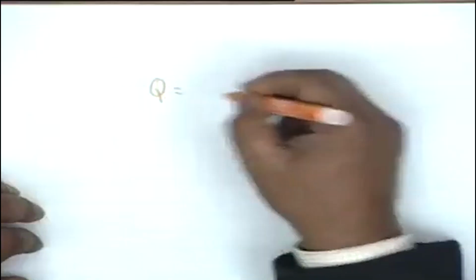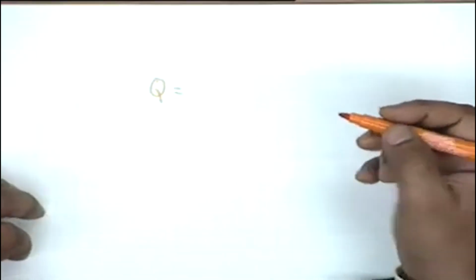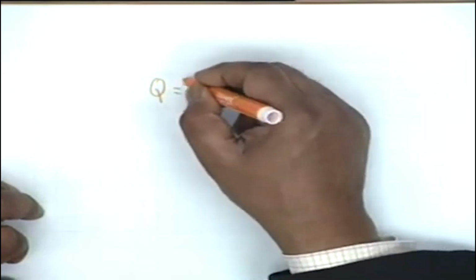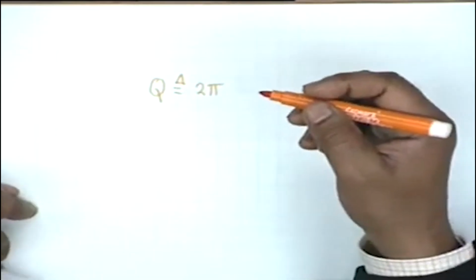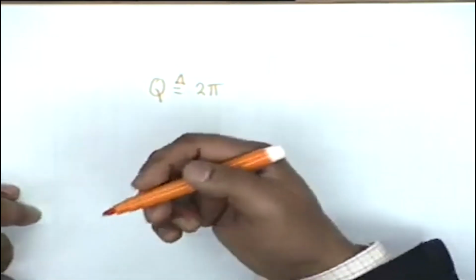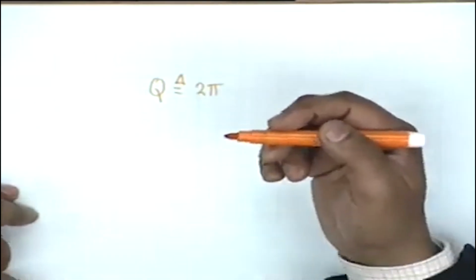and therefore it appears that if we wish to use the parameter Q to characterize the merit of an inductor or the lack of it, all right, then a more universal definition is needed, and this definition for any circuit, any inductor or capacitor, is formally given in terms of energy. Q is for quality, or figure of merit.